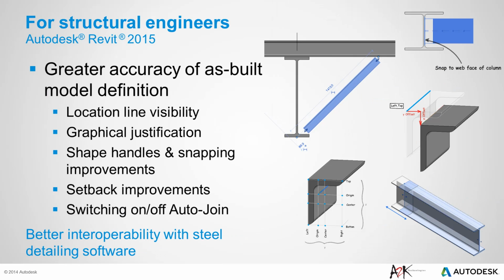There are some new capabilities and features to enable a precise definition and placement of structural framing elements in space. You can align the end of a joined beam to another beam, structural column, or structural wall. You can also reset beam ends that have been previously aligned. Now you can disallow joining behavior to structural framing elements or in as-built conditions. When disjoined, a structural framing element can snap to characteristic points along the geometry of another structural framing element.